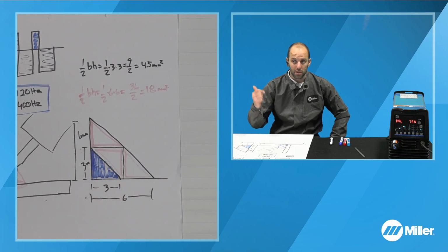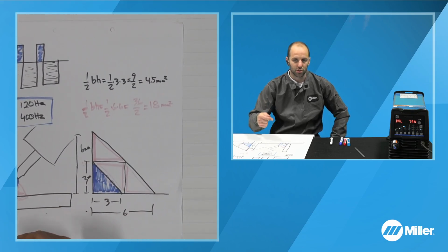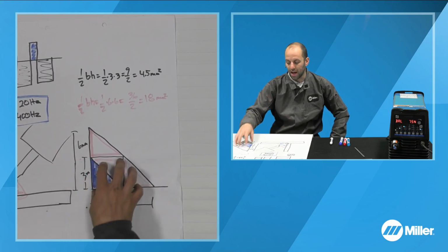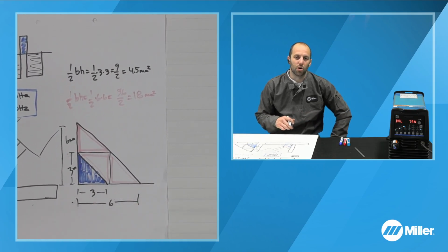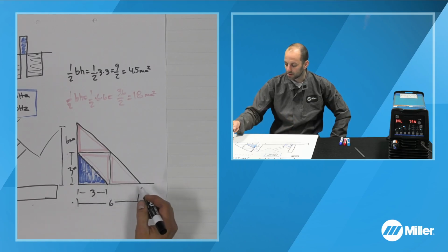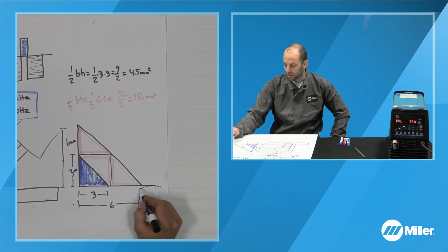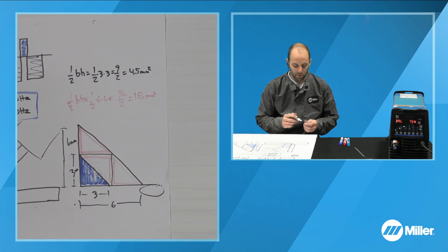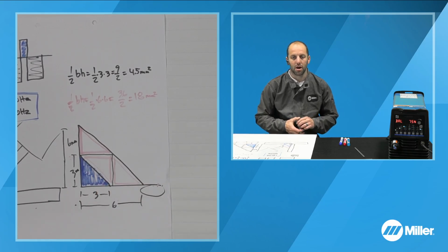If you're a welder, you're having to manually feed that filler metal into the puddle, so now you have to feed 4 times as much to get that joint done. It's more gas. There's a lot more heat that goes into the part. We covered this in the past. The heat affected zone on aluminum is actually where your weld is typically going to fail. So with more heat into the part, your heat affected zone out here in your base material is going to be a lot larger, and that gives you a larger annealed area in the material that is going to cause a larger weak point, not give you as much structural integrity.